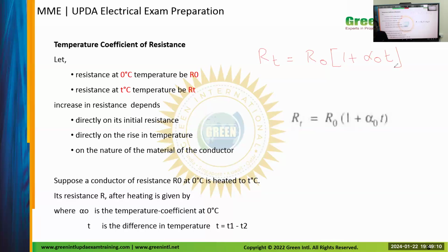This is one example. In another example, suppose we are working in a chemical plant and we need to measure the temperature in the boiler. How to measure it? Usually we use a thermometer with a maximum of 100 or 120 degrees. Suppose we need to measure 1000 degrees Celsius. How to measure it? By using this formula. Assume we have a resistance which at 40 degrees is 10 ohm. If it is inserted in the boiler, due to the temperature the resistance value changes.